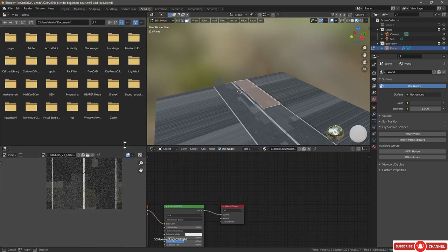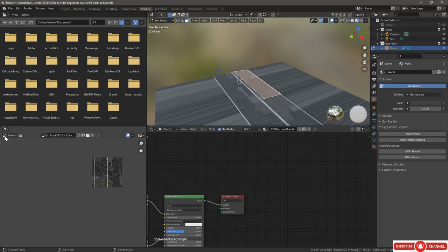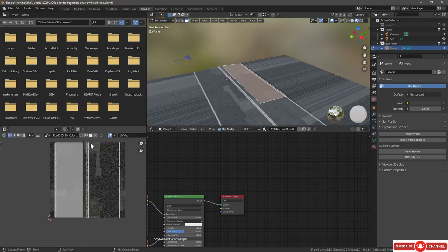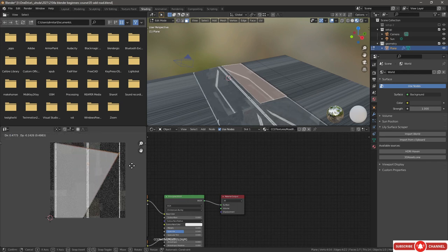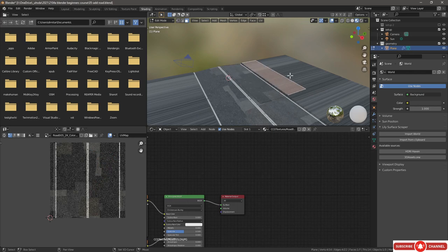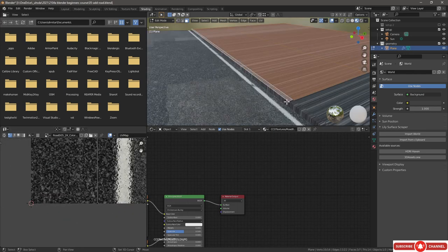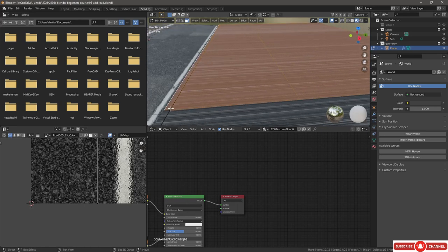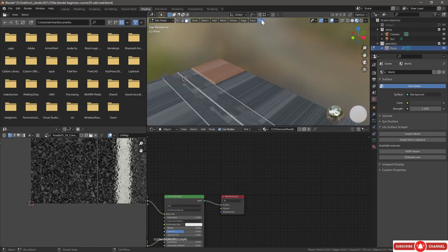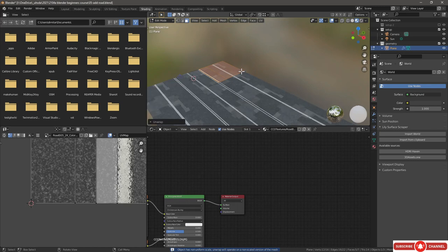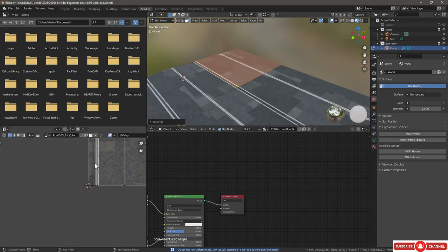Let's change this a little bit over so it's easier to see. So with the UV editor, we see where this face occurs within our texture, right? So if I move a corner around, you see the whole texture sort of gets distorted. Now, if we click on these faces, they actually are a thin line at the moment. So if I shift click this face, and also that little face here, and then go to the UV and then unwrap, and you see now it looks a little bit more manageable. They're all unwrapped within here.